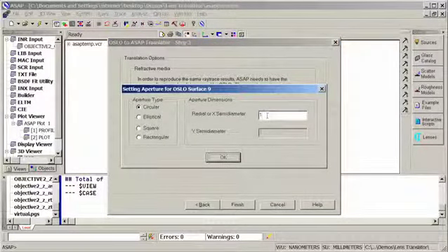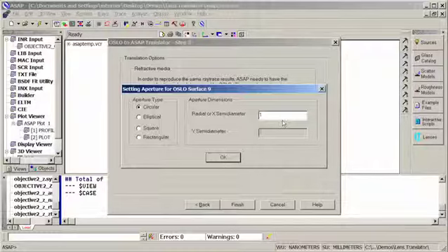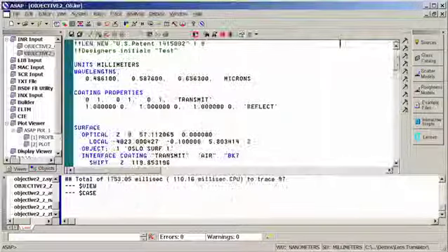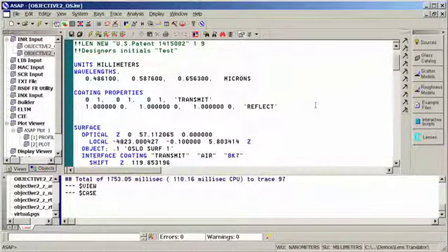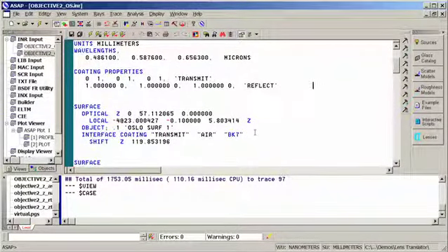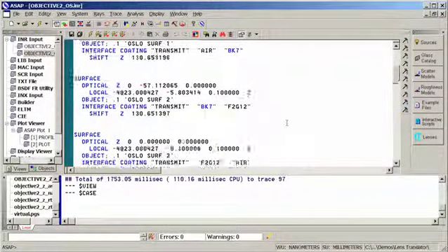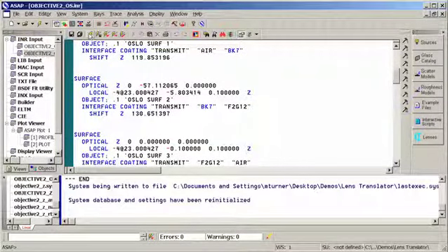In this particular case, I was given an indicator that the designer hadn't put a size to the actual image plane. And I know I'm going to have an image of a 17mm size, so if I put it in right now, I don't have to remember to do it later. And again, ASAP finishes up, and I see the information about my surfaces, my optical materials. And now, same, let's just run the file and see what it looks like.